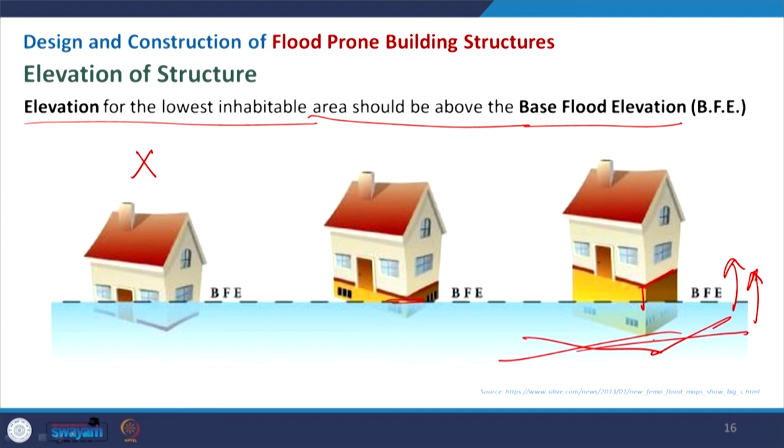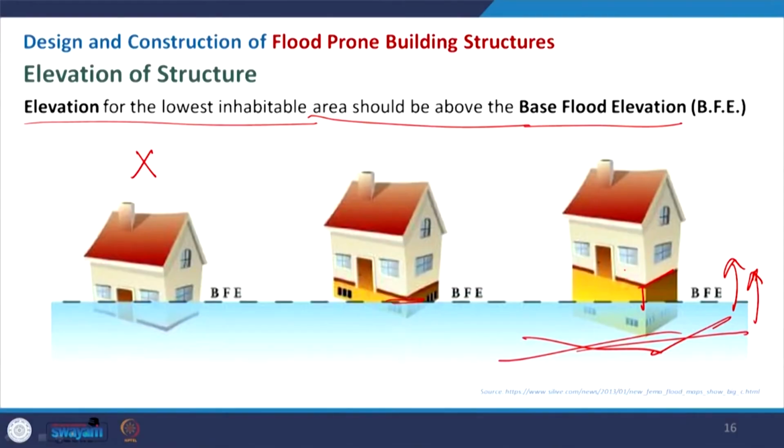You can easily make your plinth low, but if we consider the risk associated with this flooding situation, it may occur occasionally, means unpredictable, then it is different. But if you know that your site where you will make your building really has this threat of waterlogging or flooding, then definitely spending a little bit initially will really save a lot in the long run. So you can really sustain during this situation.